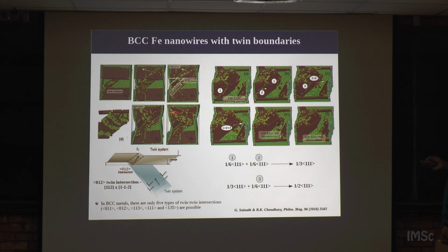So, basically whether it transmits to the next grain or not depends on the transmission strain, and this is where you can see the twin boundary acts as a nucleation site for a dislocation. So, this is something like a curved twin boundary in BCC, and with increasing strain these partials will come. This is one partial, you can see here, it came and accumulated here, and the next partial comes, that also comes here, accumulates here, and then again a third partial will come and accumulate. Now, once the third partial comes, that leads to the formation of a full dislocation, which dissociates from the curved twin, and so because of that the initial twin boundary becomes smaller in size.